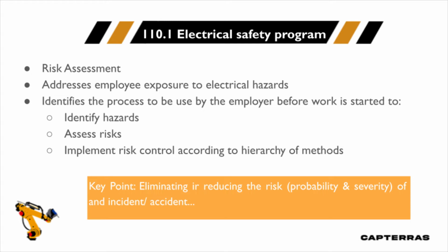If I'm going to switch a 1200 amp breaker on, even with the covers on, I may be standing in front of a bunch of vents and may say, I'm going to make the assessment here that the arc flash energy could come out through those vent holes if something goes wrong, and I'm going to go ahead and wear the full PPE as if the doors were open. So again, each person should be able to make an assessment. Now, I get so many people that want to turn this into a black and white thing. In other words, we have to do this here or we don't have to do it here. No, it's up to each one of us to have enough information to make judgment calls.